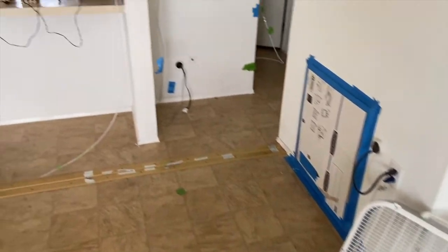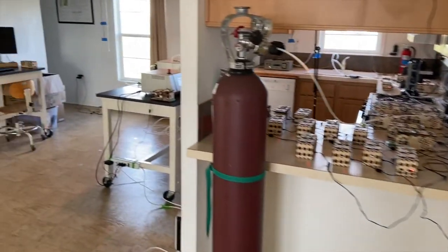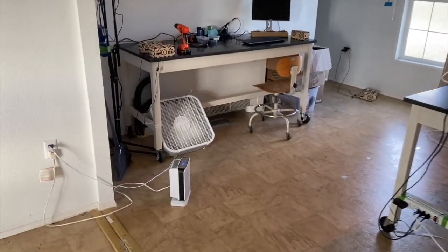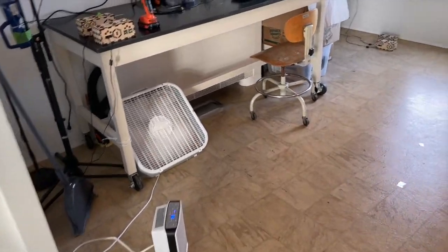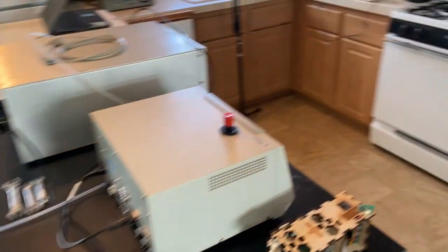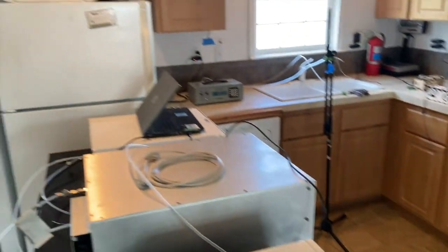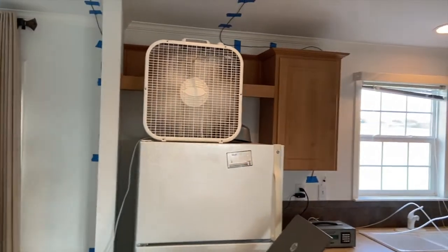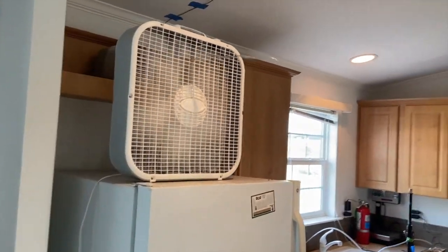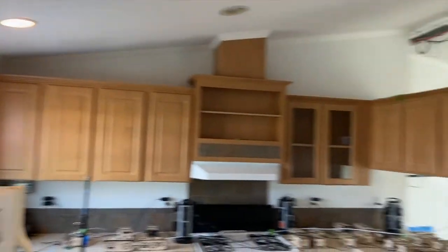Now I'm going to inject CO2 into the same place back in the kitchen, but this time I'm going to turn on those box fans as well as the ceiling fan to help induce some mixing, and so hopefully the concentrations at those perimeter areas should match up with the concentration measured right at the exhaust much quicker. And that will get us to the well mixed condition, and we'll see how long it takes for that well mixed condition to actually be valid.